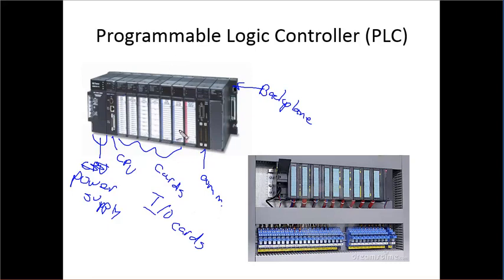So we talked about the analog to digital conversion process, and we talked about current loops, right? So the I/O cards, there are typically multiple types of I/O cards available for a PLC. You'll have analog input and output cards and digital input and output cards. A digital signal would be like a digital input card. What you would do is wire, say, a push button switch to it, or maybe a breaker closure or something like that. And so you could sense whether that button was being pushed or whether that breaker was closed, and that would be a digital input, right? Remember, our digital inputs are on or off.